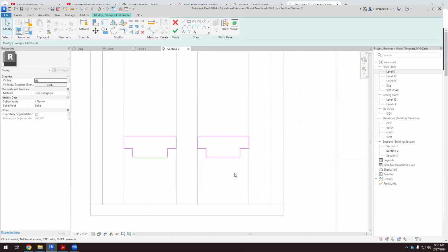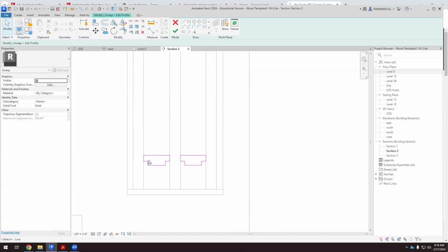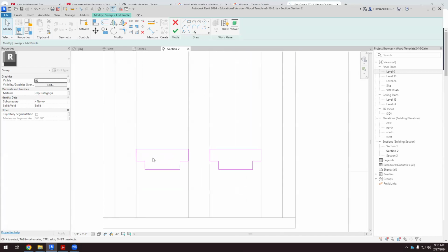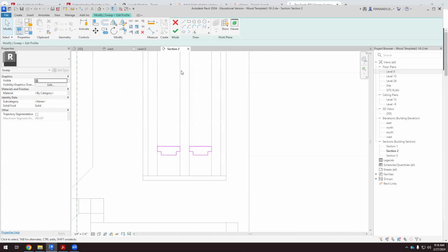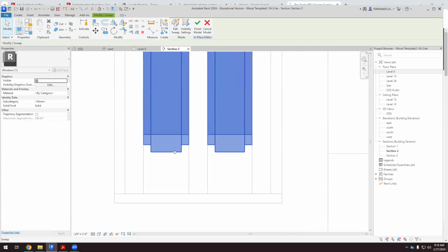Okay, so that's the shape of the spacer, kind of. I'm not going to explain why it has this shape, but that's the shape of the spacer. So we finish twice. And what's the material of this? Well, that's a good question. Usually it's made of aluminum. But nowadays, they are improving a lot of things in glazing, so they have made this of a thermal insulating material, something that is kind of a plastic.